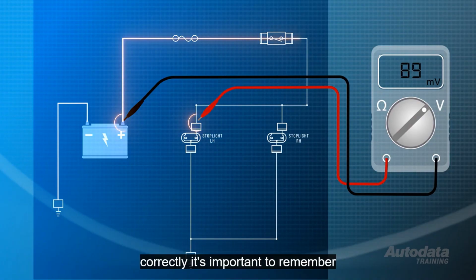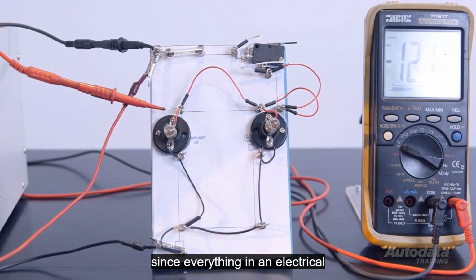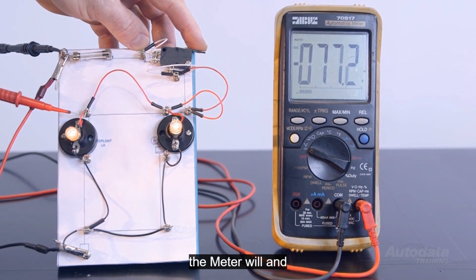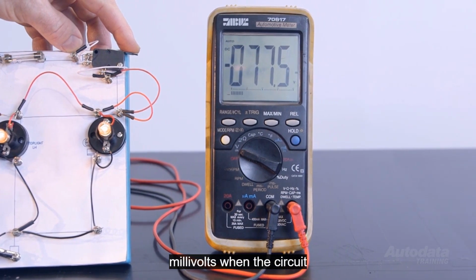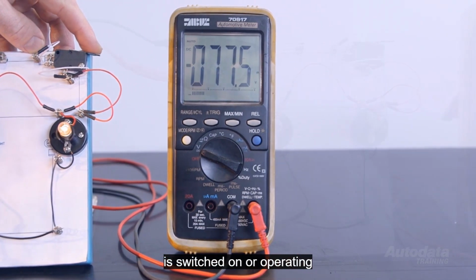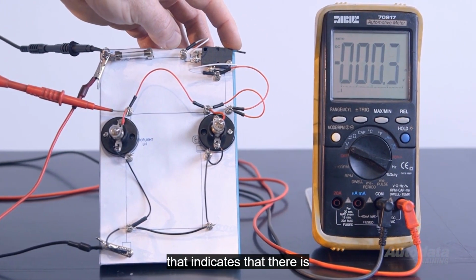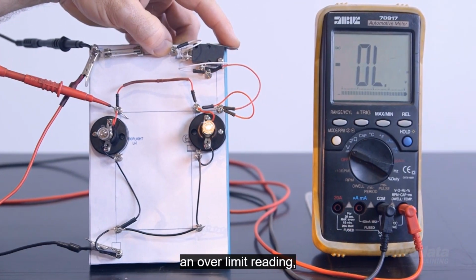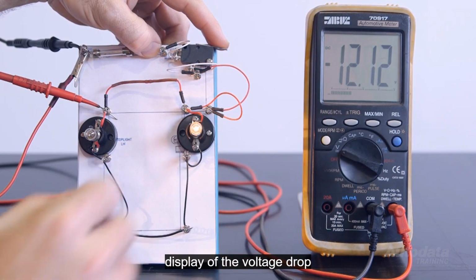It's important to remember that this test is only going to check the dynamic resistance of the circuit between these 2 points. Since everything in an electrical circuit offers some resistance, the meter will and should display a small voltage reading, less than 500 millivolts, when the circuit is switched on or operating. If the meter displays a perfect 0 volts, that indicates that there is no current flowing in the circuit. If the meter indicates an over limit reading, switch it over to DC voltage for a more accurate display of the voltage drop.